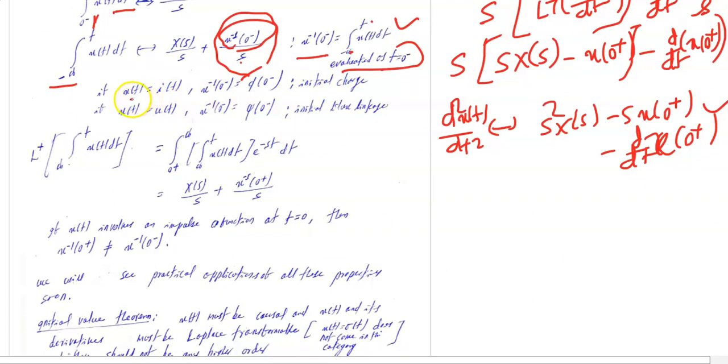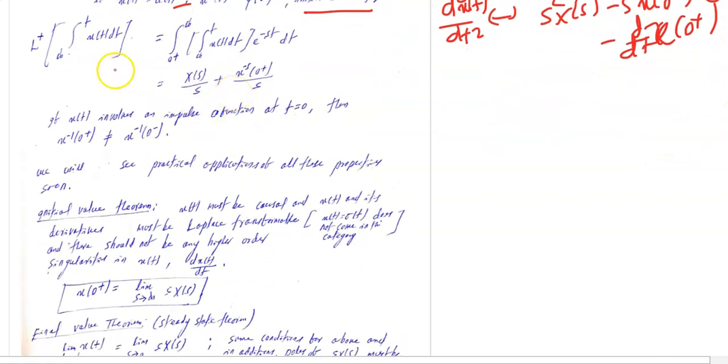So this is when x(t) equal to i(t). See here, x(t) can be i(t), so integration of i dt will be the initial charge. Similarly with v(t), the integral of v dt will be the initial flux at 0 minus. Or when the switch is closed, we see the same thing, only the difference is 0 plus versus 0 minus, but 0 minus we are least interested in because we are considering the circuit at t equal to 0 plus.